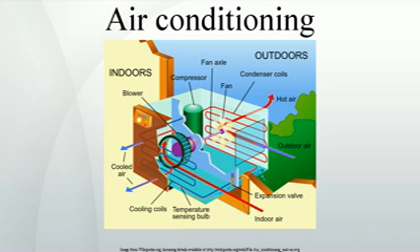Hose systems, which can be monoblock or air-to-air, are vented to the outside via air ducts. The monoblock type collects the water in a bucket or tray and stops when full. The air-to-air type re-evaporates the water and discharges it through the ducted hose and can run continuously. A single duct unit uses air from within the room to cool its condenser, and then vents it outside. This air is replaced by hot air from outside or other rooms, thus reducing the unit's effectiveness.